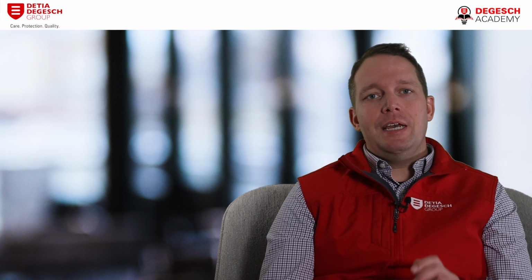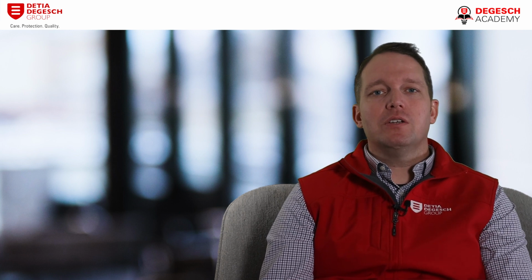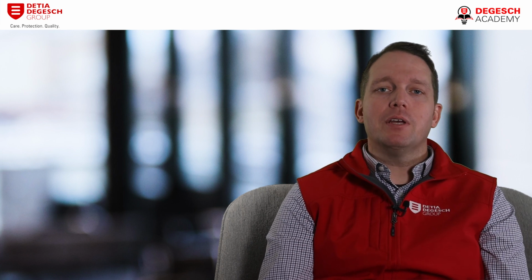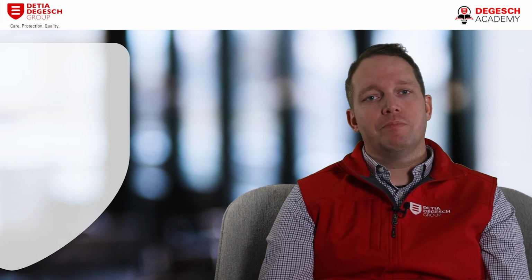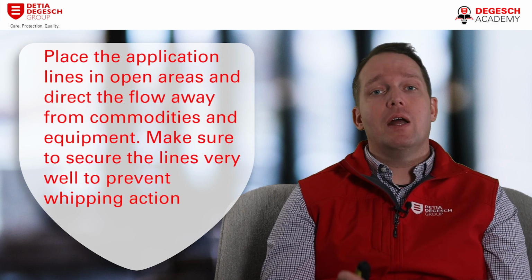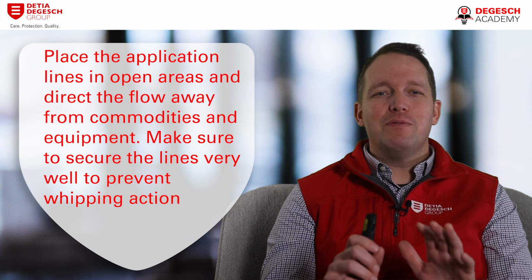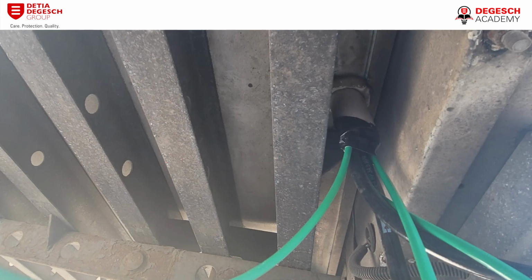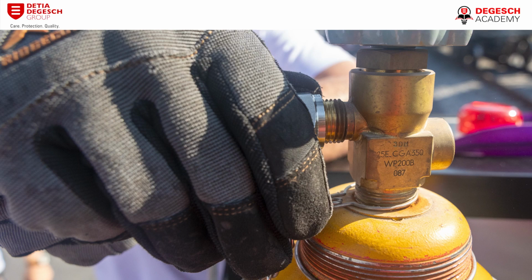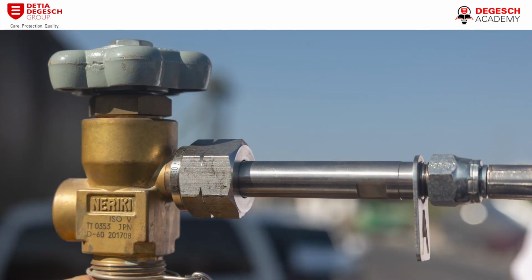However, if there's ever a question, especially in a multi-floor or heavily compartmentalized structure, multiple application points will need to be considered. Place the application lines in open areas and direct the flow away from commodities and equipment. Make sure to secure the lines very well to prevent whipping action. Then run the application end out of the staging area and to the exterior of the facility and connect them to the phosphine cylinders or the blending equipment being used to apply the phosphine.